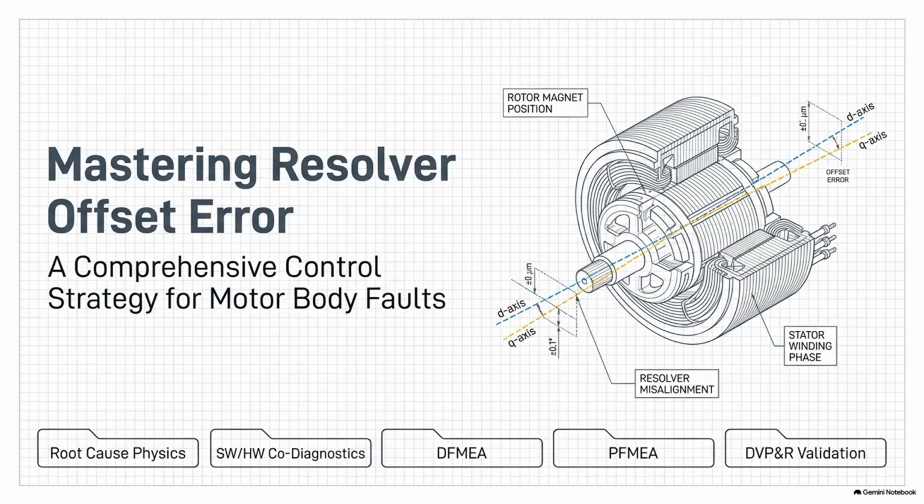When that magnetic push is exactly perpendicular to the rotor's magnetic axis, you get maximum torque. Think of it like pushing a revolving door. Oh, I like that analogy. Right, so you want to push at exactly 90 degrees to the glass to get the most leverage. If you push at an angle, you're just wasting energy, basically compressing the hinges. You're just shoving the door into the center pillar. Exactly. It doesn't move the door, it just stresses the hardware.